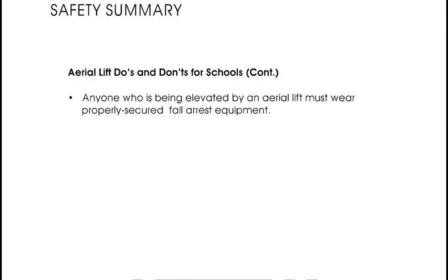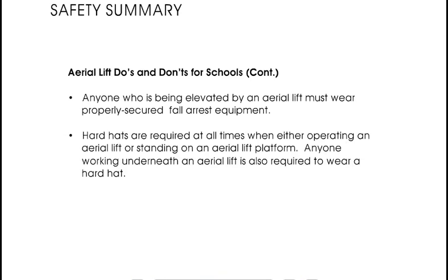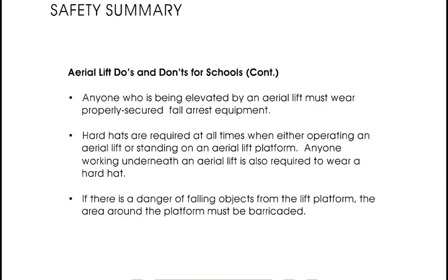Anyone who is being elevated by an aerial lift must wear properly secured fall arrest equipment. Hard hats are required at all times when either operating an aerial lift or standing on an aerial lift platform. Anyone working underneath an aerial lift is also required to wear a hard hat. If there is a danger of falling objects from the lift platform, the area around the platform must be barricaded.